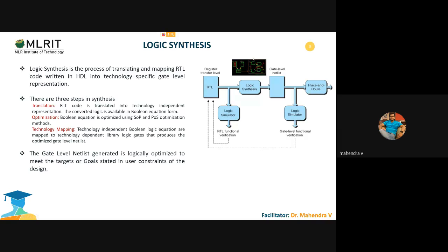Now that is the logic synthesis process. Here, synthesis simply converts the Verilog code into the gate level netlist. While doing that, you do this process. Now after the gate level netlist, again we do verification. That is gate level functional verification, which I already explained enough times in my previous classes also. Now, is it good to go next?